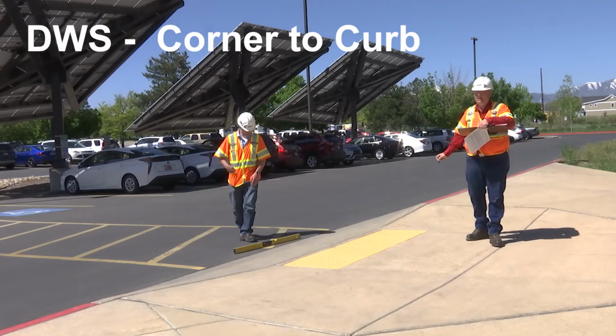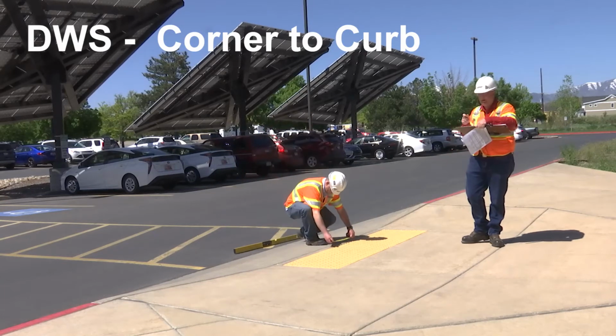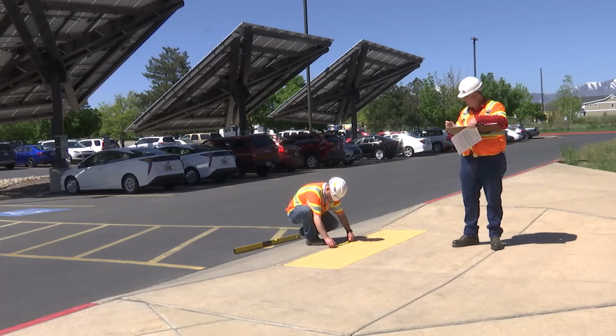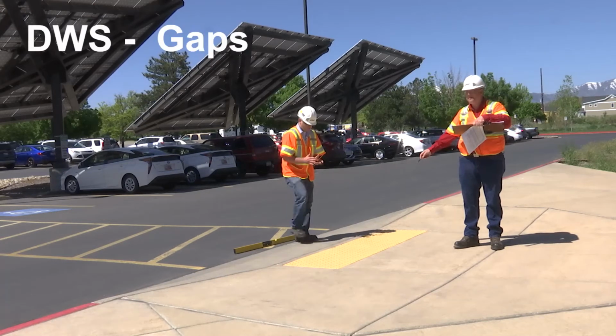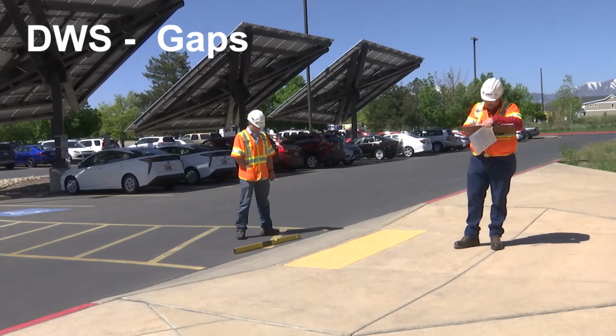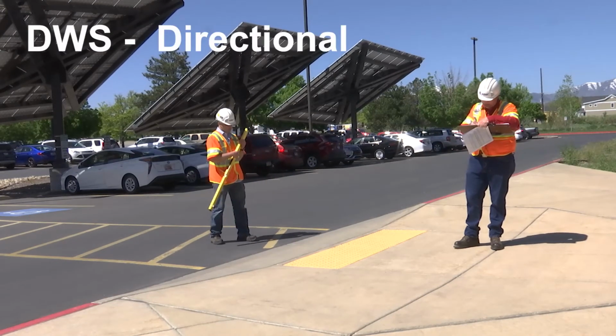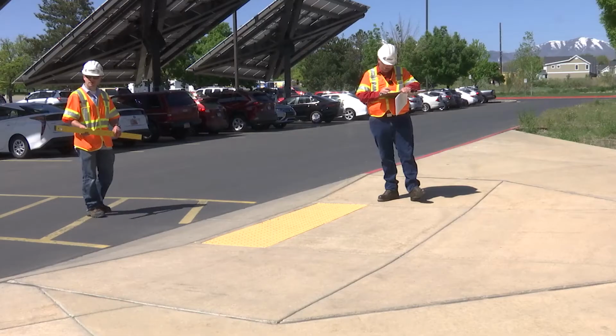The same thing on the other side. We're under 2 inches, but we're still 4 inches away from the top back of curb. So next we check to see if there are any gaps, and we can see that there are no gaps between the panels. We're under 2 inches, and so we will circle yes. And this is not a directional case, so we put NA there.